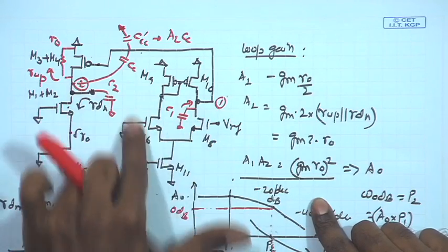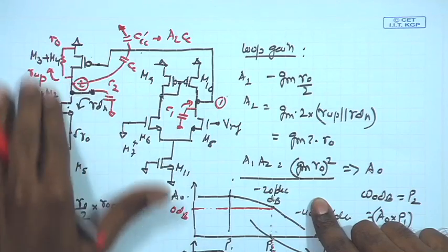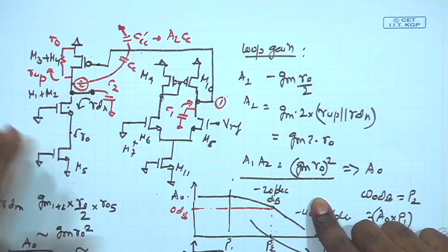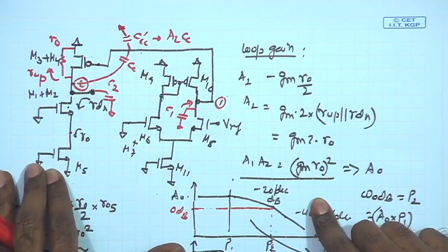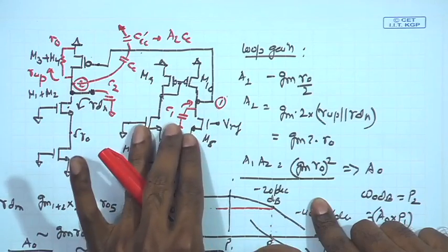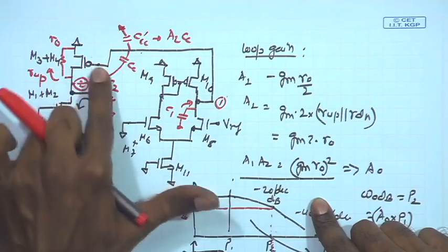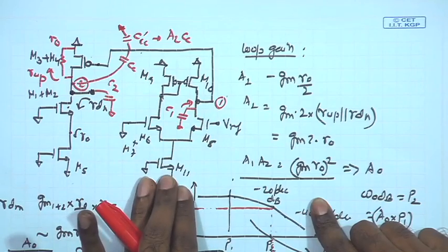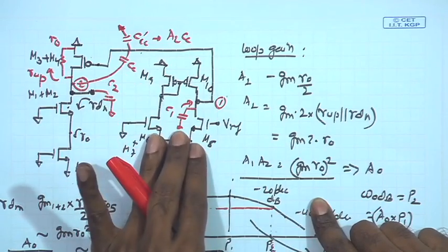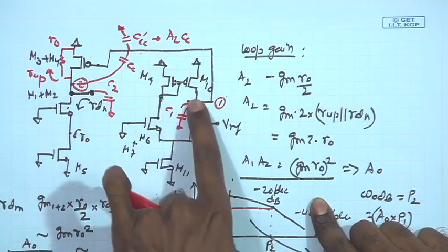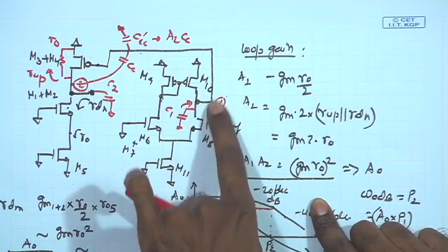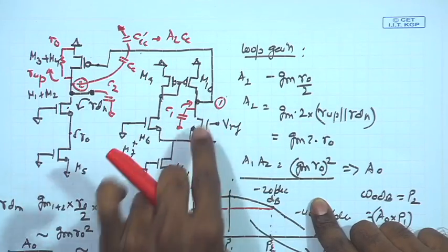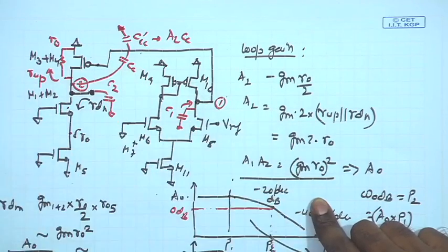Here noise constraints are also less critical. In the main differential amplifier you have a noise constraint, because of which you cannot reduce the bias current too much, but in the common mode feedback amplifier it is less critical, because whatever noise comes, it comes in the common mode. Because of that you can reduce the bias current of this one more aggressively, and you can apply longer channel length as well, so that the RO of this stage becomes the dominant one. That will help you in pushing pole 1 to low frequency.